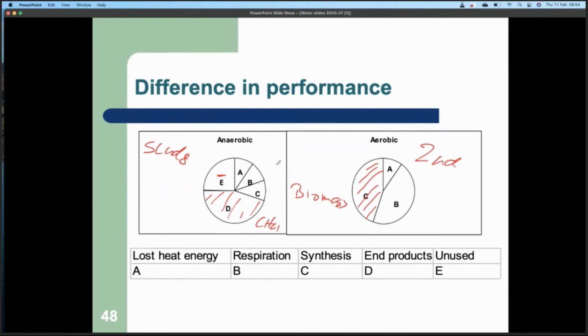So that's why you would normally not find anaerobic bacteria on a conventional treatment works, and you would only find anaerobic digestion in the sludge treatment of treatment plants. So that's the secondary treatment done, which tends to be the aerobic treatment. There was a quick side stint onto anaerobic treatment, as in sludge treatment. And then I'd like to look at the anoxic treatment a little bit more in the context of the whole biological treatment.